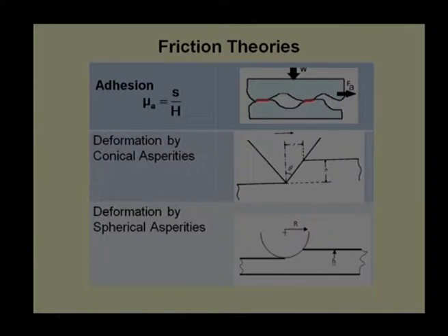Lower the shear strength of material, higher hardness will provide lower coefficient of friction. However, we discussed also what the drawbacks are. As I mentioned, if the same material has been used against a number of pairs, this theory will provide the same coefficient of friction for all material pairs, which is not right.